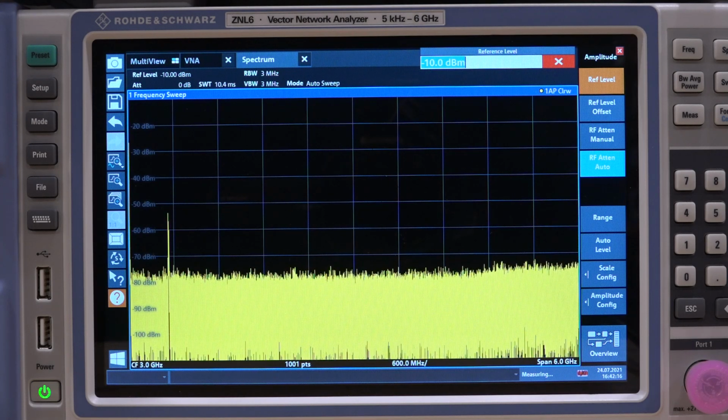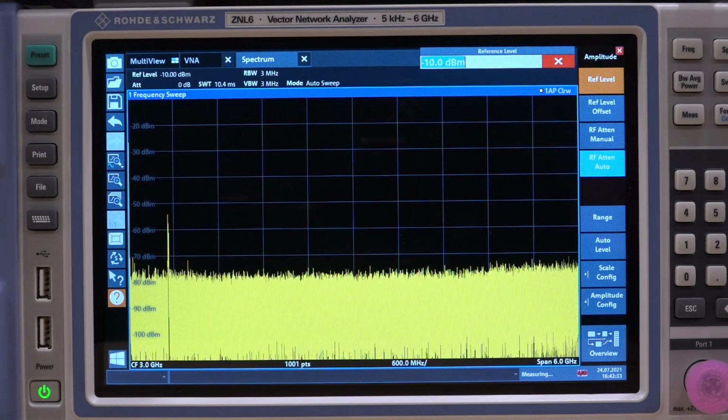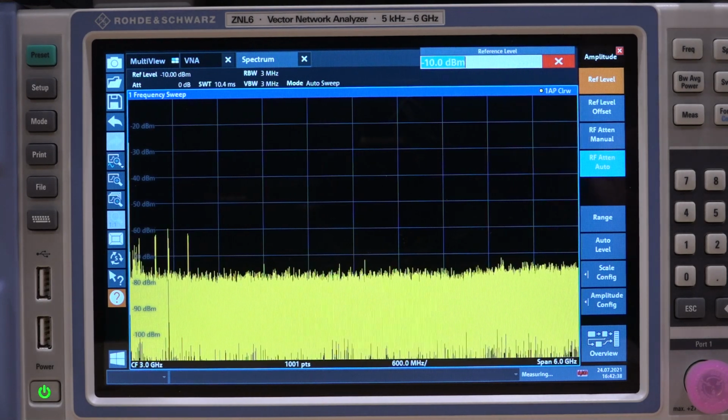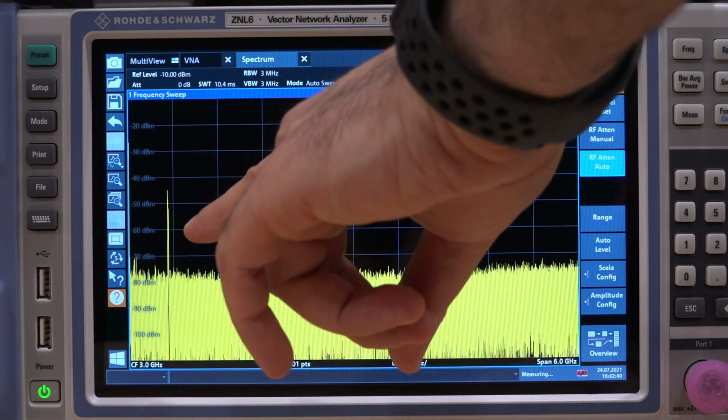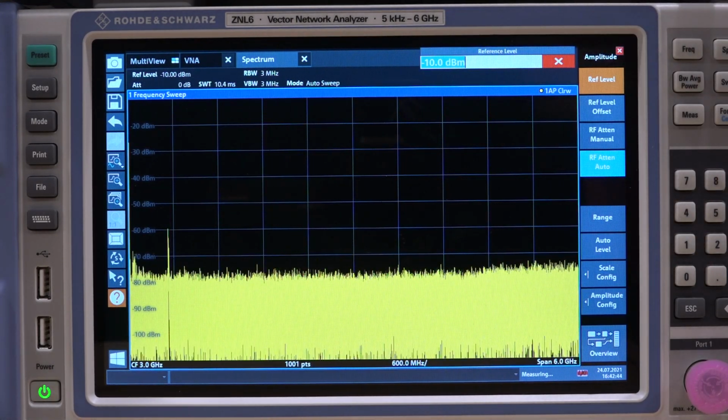Okay, so let's go ahead and land directly on the VCO output. Now, what do we expect if the VCO is working? First of all, we expect the signal around 3 gigahertz, but we also expect that signal to be jumping around quite a bit, because we saw that the tune voltage of the VCO was jumping around because the PLL is trying to achieve a lock. That's kind of what we're looking for too. There's a difficulty in landing, so it's not going to look very good at the beginning. Also keep in mind that this big signal you see here at 548 megahertz is my wireless microphone. You're going to have to ignore that one.